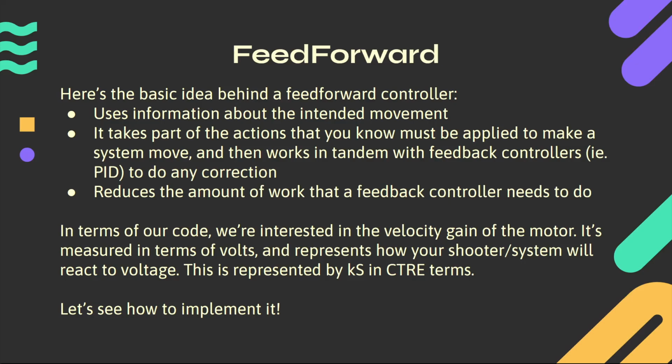But in this case, we're really focused on combining feed forward and PID to leverage the fact that we have an idea of the kind of velocity gain that we want on our motor. So let's apply this gain and trust that the gain is sufficient to the point where the PID controller doesn't need to do that much work in terms of correction.